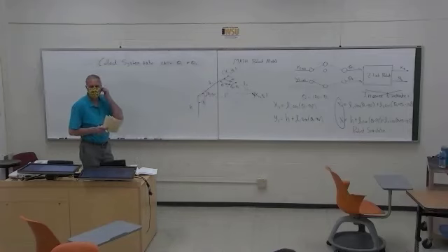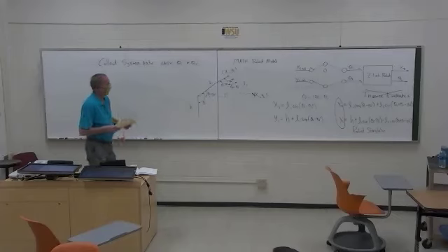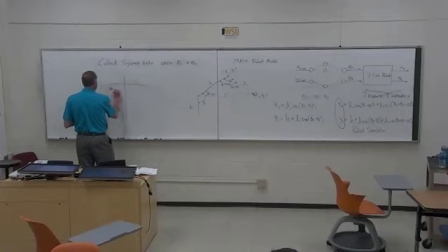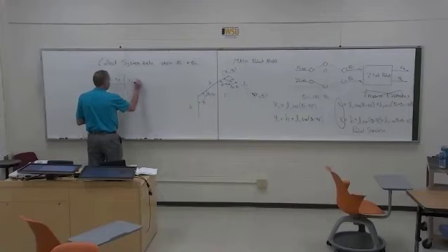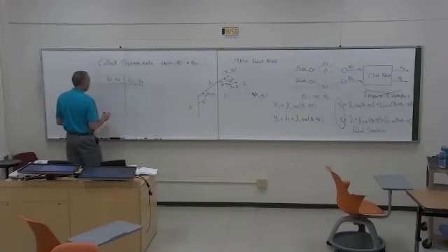But for a general system, this may be harder to do, because you don't know what inputs lead to what outputs if you don't know the system itself. So we vary those, and then you end up with a set of data. You input some theta values, and then you get x2, y2 values collected from the robot. So you have data.